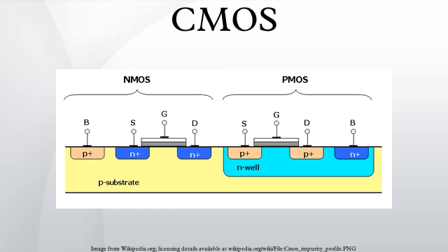In short, the outputs of the PMOS and NMOS transistors are complementary such that when the input is low, the output is high, and when the input is high, the output is low. Because of this behavior of input and output, the CMOS circuit's output is the inverse of the input. The power supplies for CMOS are called VDD and VSS, or VCC and ground, depending on the manufacturer. VDD and VSS are carryovers from conventional MOS circuits and stand for the drain and source supplies.